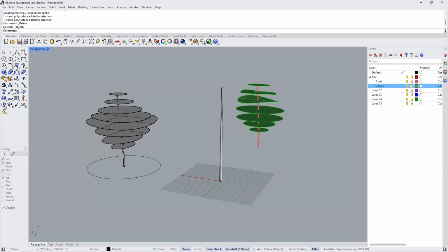Another idea also, you can create another shape, and I believe it's this one, the ellipsoid. One second. And I think ellipsoid from center is the one I want to pick. So I'll just type 0 as the center point, and I'll pick a point out here. I'll pick a point there, and then I'll give it some height like this.